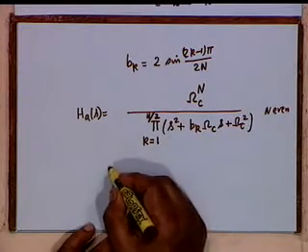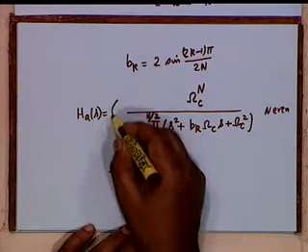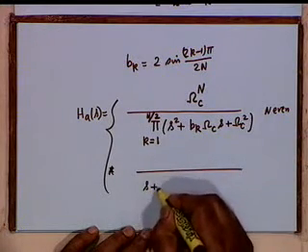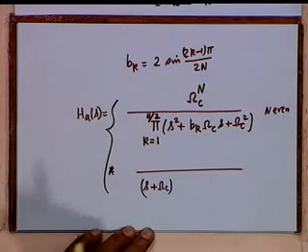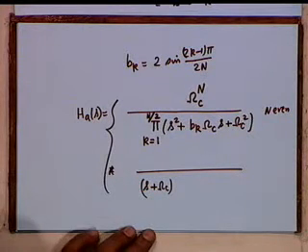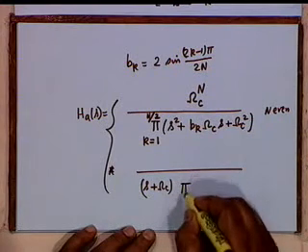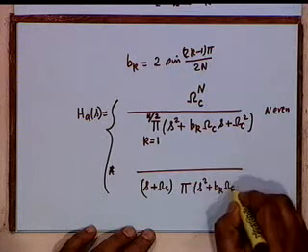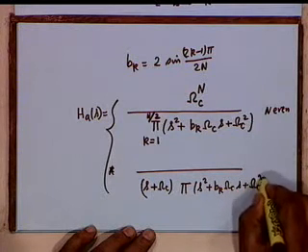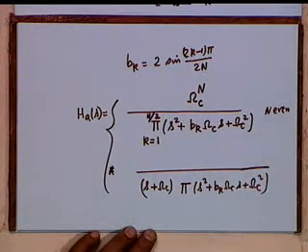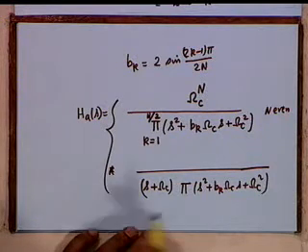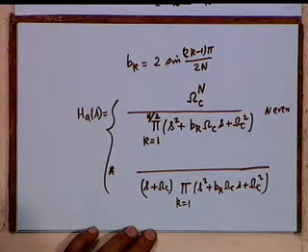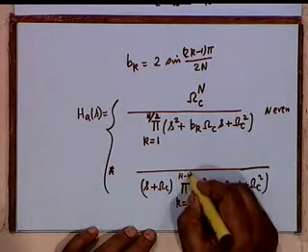All right. On the other hand, if n is odd, then it shall be S plus omega c. There must be a pole at omega c, one real pole, and then the continued product, the same factor, S squared plus bk omega c S plus omega c squared. Now k will go from 1 to n minus 1 by 2.